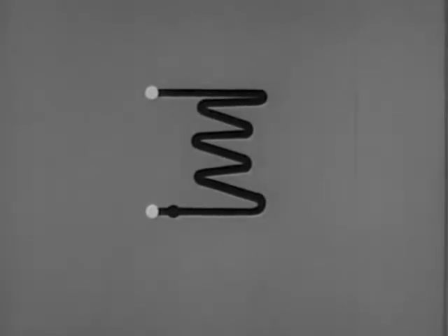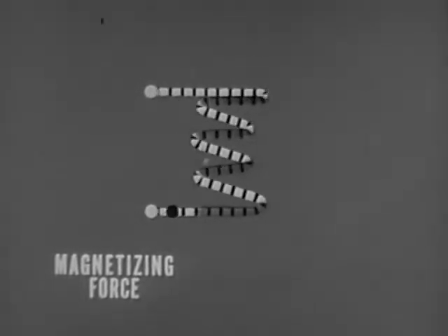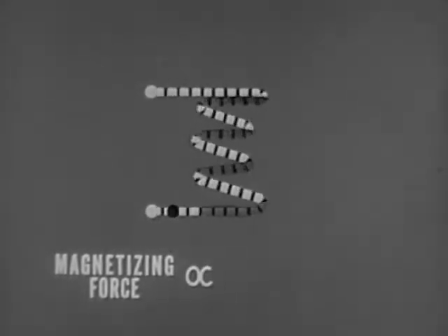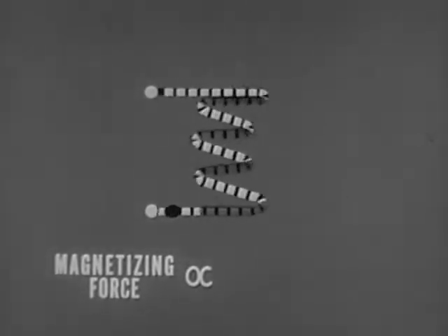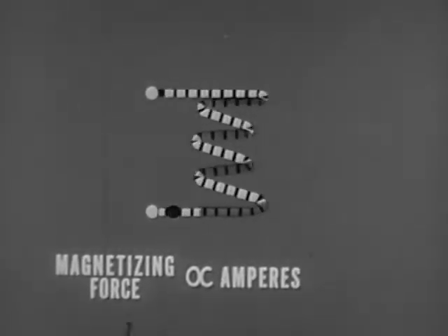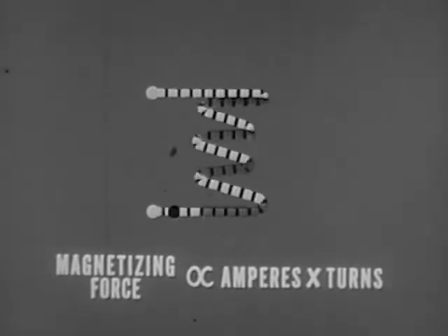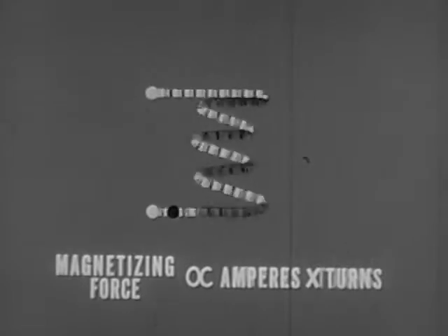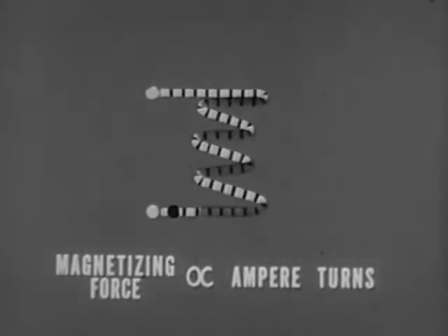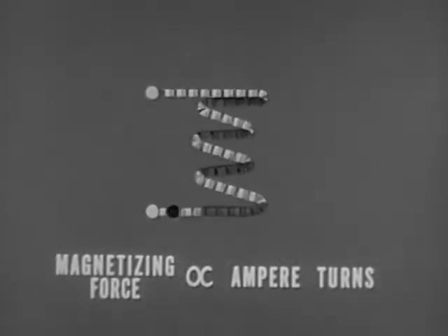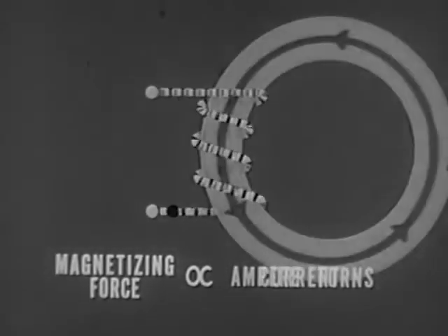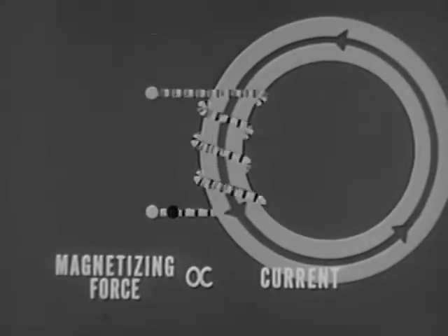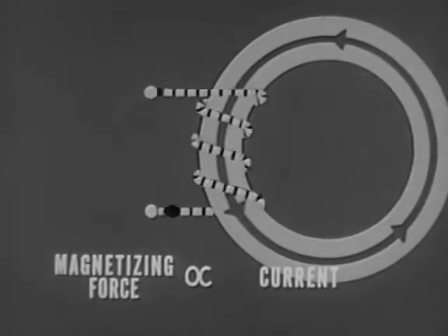Any winding around the core obeys the laws of electromagnetism. The magnetizing force it exerts is proportional to the amount of current flowing through it, measured in amperes, times the number of turns in the coil. Or, as it is usually expressed, the ampere turns. Since the number of turns in this winding is constant, we can simplify the rule here. The magnetizing force exerted by the winding on the core is proportional to the winding's current.